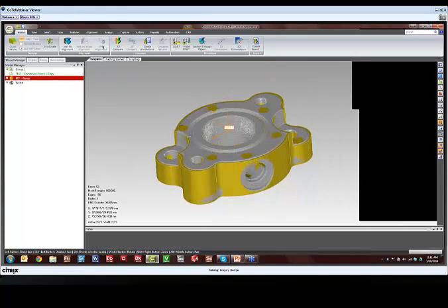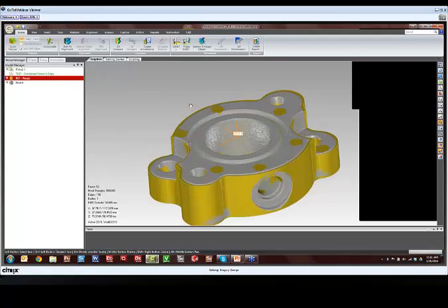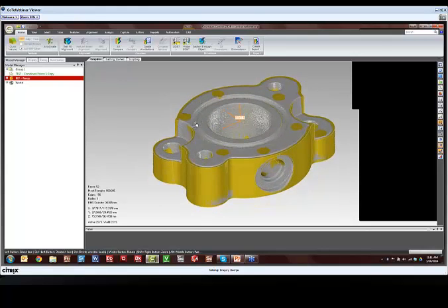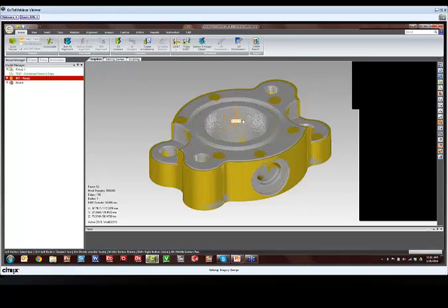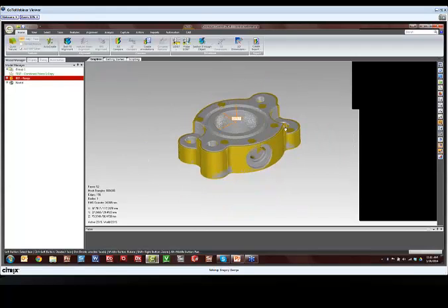RPS alignment is a reference point system. That's kind of like virtually setting the part inside of a point nest, similar to an automotive style alignment, where you have points and it's going to register the object based on those locations only. But for today, I'm just going to keep my best fit alignment, and we'll work from there.